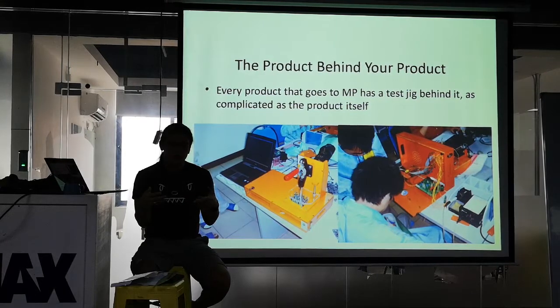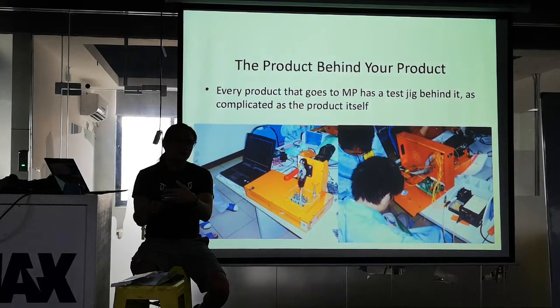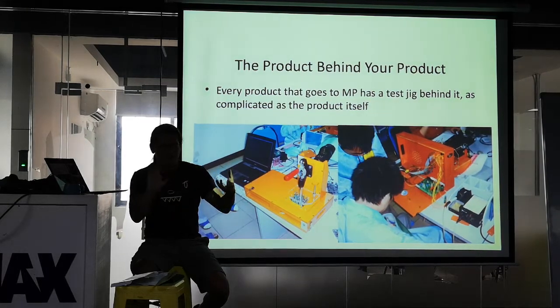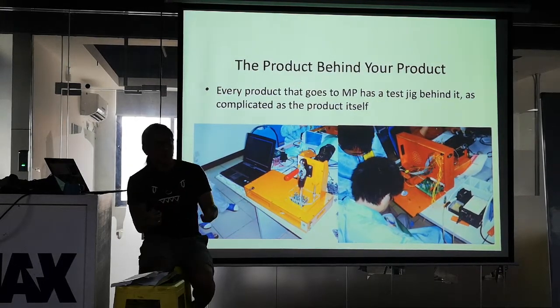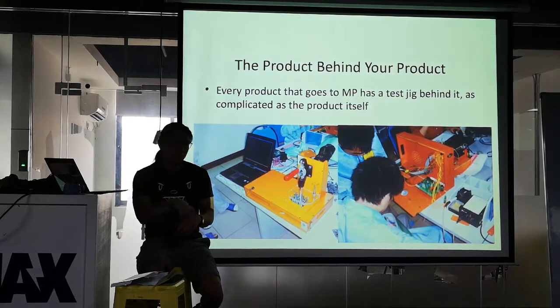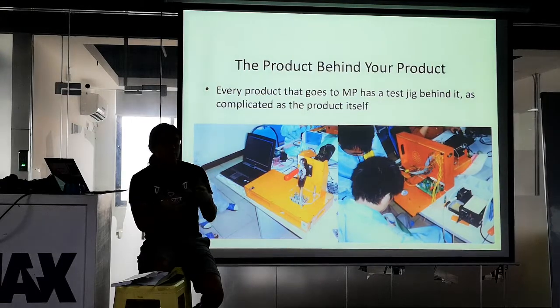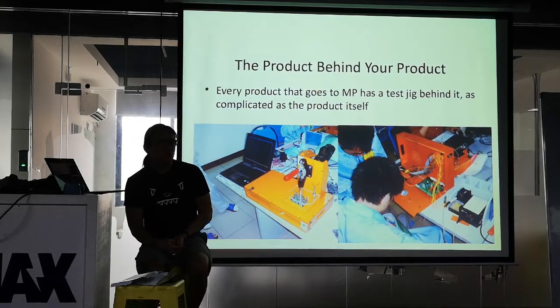These are a whole bunch of single point programs you wrote anyways, right? You had to do this to even know if your board worked. So the concept of Sean's infrastructure is to take this collection of programs you wrote already, run them in a sequence in a scenario, and that becomes your factory test. So you're not having to write things twice. Xclave is essentially a shell script sequencer. If you do your bring up using Windows or Bash or Linux, just keep a record of all the scripts that you ran. You can then install Xclave on a Raspberry Pi, load those scripts on it, and it'll do all of those for you in sequence at the factory. So there's more automation happening in this area to help you, and that would be ideal.